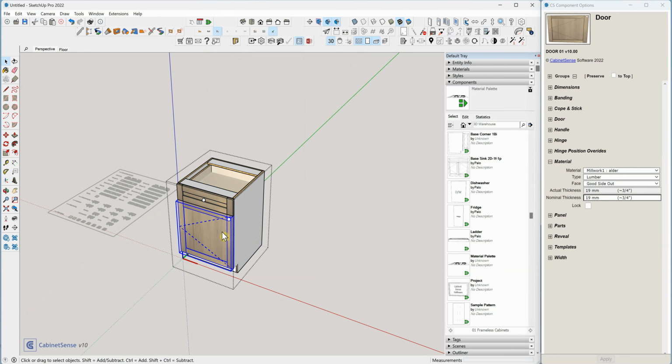If our construction method is always to use the same material for our drawer box, we can use references. So what I will do is I will say, use the same material as carcass 1. Now if I change carcass 1, and I'll just change the A side back to melamine white, everything changes.